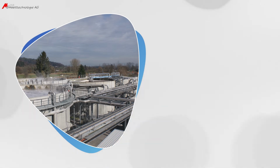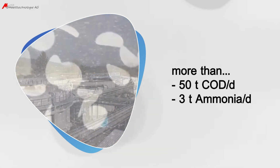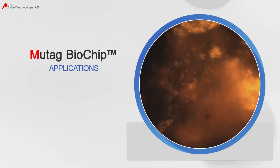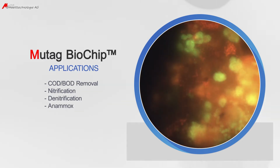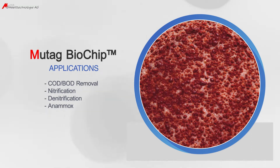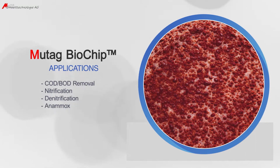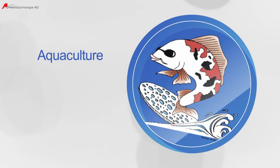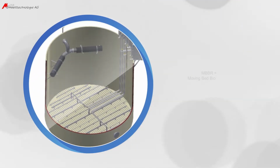There are MBBR plants which are treating more than 50 tons of COD per day, or more than 3 tons of ammonia per day. The Mutag BioChip is used for water and wastewater treatment in general for COD or BOD removal, nitrification, denitrification and also for NOx application. It is also used in many aquaculture applications for denitrification and nitrification too. It can be used in MBBR-based plants or in combination with activated sludge as IFAS system.